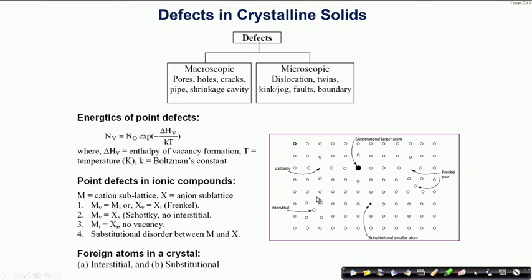And the portions which are left out, for example here, will have a certain dimension, and if you try to fit another sphere into these kinds of holes or vacant spaces, there is a limit to what you can accommodate, and the maximum diameter that one can calculate in these holes will determine the possible size of an interstitial atom that can fit in.